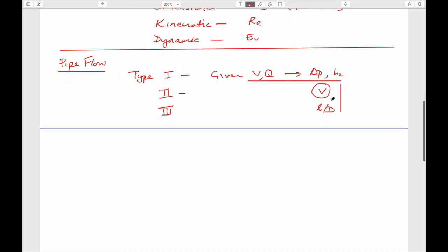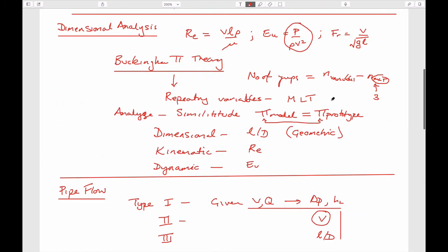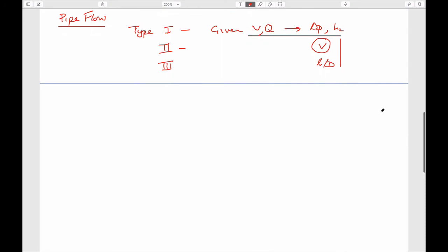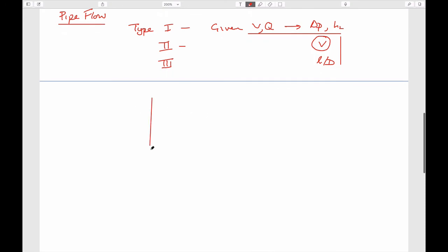We know that in looking at this expression for Bernoulli's expression, or the energy equation, we have both pumps included and head losses included, both for bends and also for pipe flows. We know that for pipe flows we can get this from a Moody chart. The essential components of a Moody chart are that it gives us a friction factor.